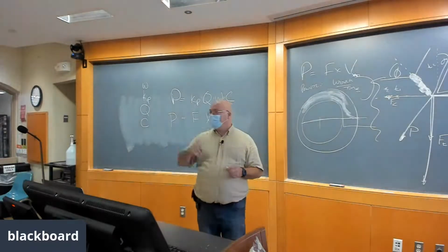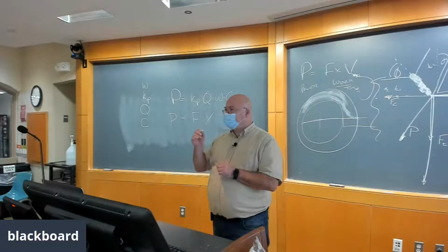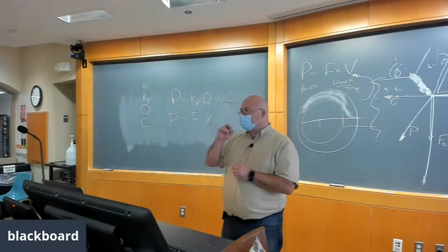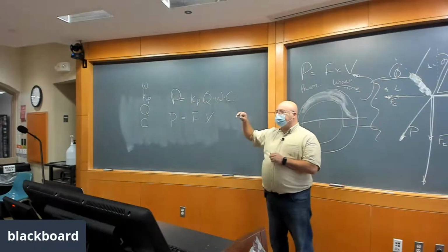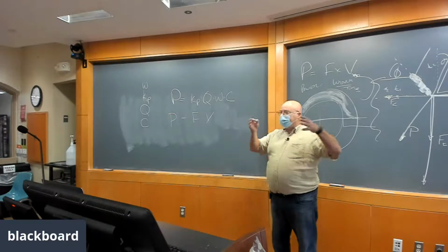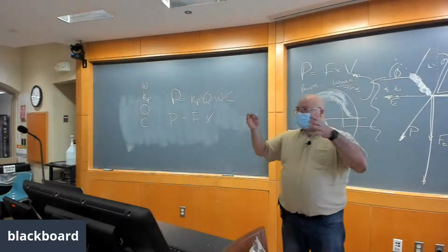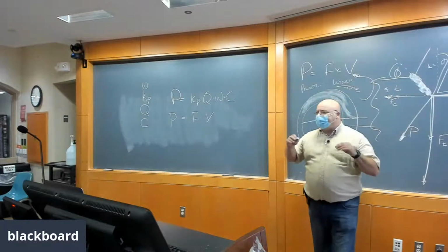I was wondering, do the material properties change a lot, like with heat? I know a lot of the small parts are relatively hot. Yes, material properties change a lot with heat, but the KP value that you're looking up in the machinery's handbook is found experimentally. So it was determined in the same conditions that you'll be doing the cutting, ish.